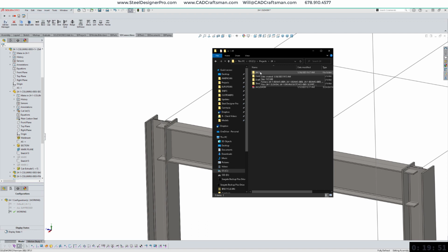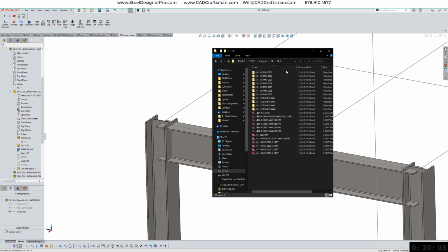The Zone folder contains all member folders and part files. The Deleted Files folder contains our connection. The Zone folder contains the welded member folders as well as the zone level parts such as grids. Connections are placed within subfolders of their respective welded members.